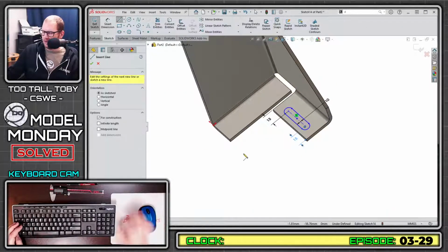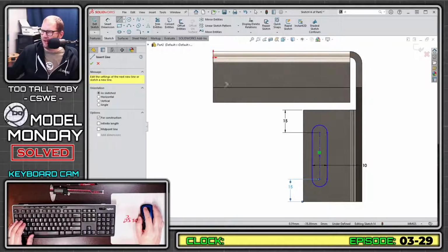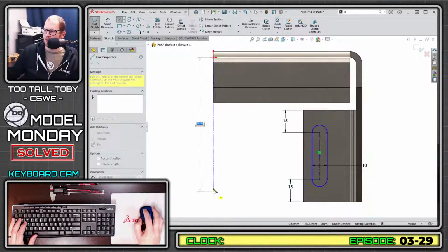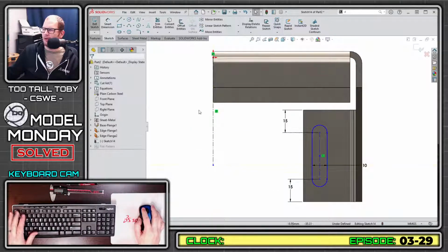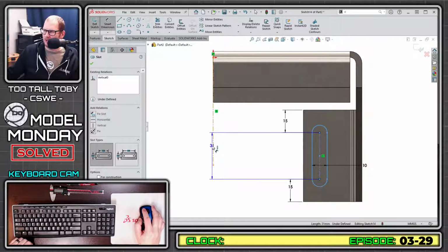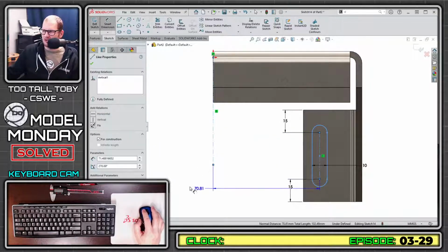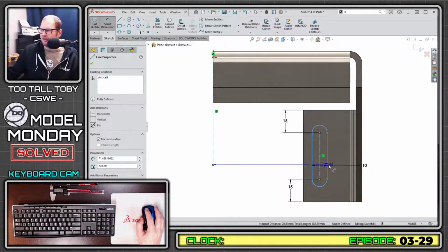And then here, again, so much of SolidWorks is these kind of nuanced pro tips. But here what I want to do is create a double dimension like I did before. So I pick this line here and I pick this line here, and the double dimension doesn't show up. Why doesn't the double dimension show up? Because I went from a center line to a center line. So SolidWorks doesn't know which center line the double dimension should go over.